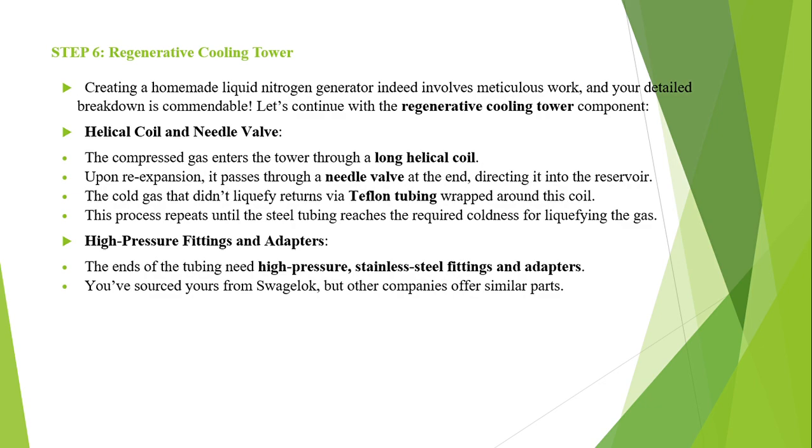Step 6 is the regenerating cooling tower. Creating a homemade liquid nitrogen generator indeed involves meticulous work, and your detailed breakdown is commendable. Helical coil and needle valves: the compressed gas enters the tower through a long helical coil. Upon re-expansion, it passes through a needle valve at the end, directing it into the reservoir. The cooled gas that didn't liquefy returns via Teflon tubing.